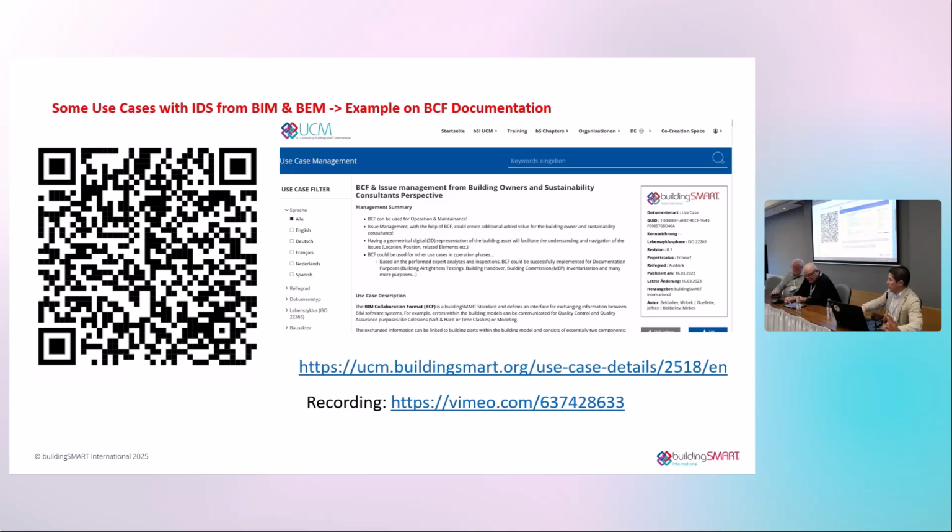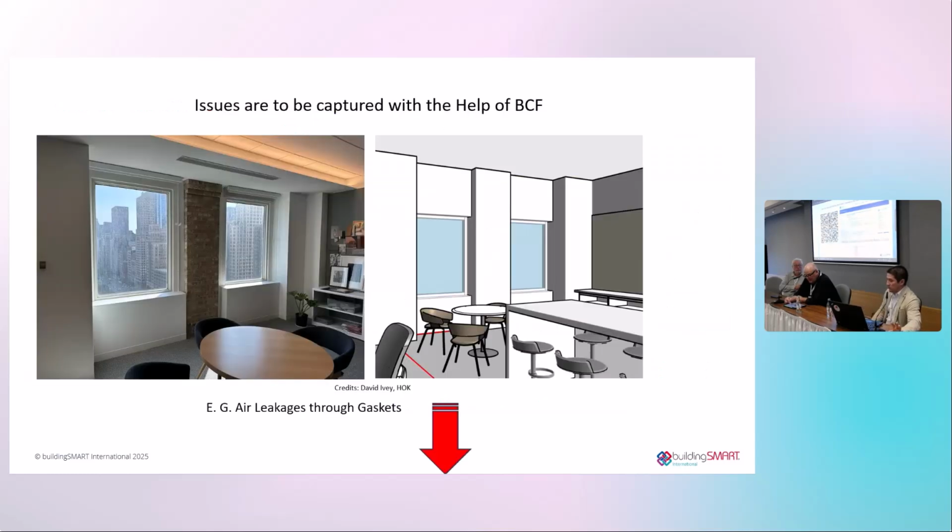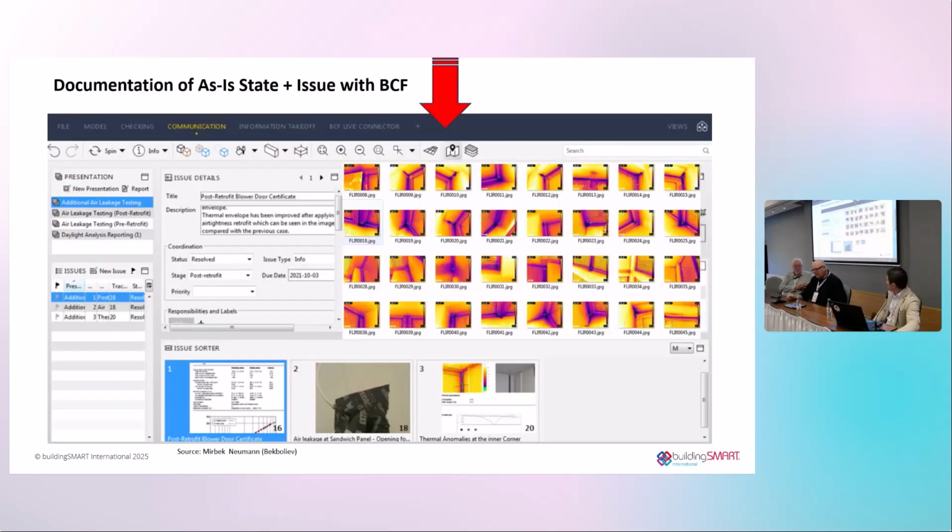You can check it later. That's what architect and client did, and it was the same case in the HOK office. So we ran a blower door test, thermal imaging, camera imaging, and as you can see, we found a lot of leakage. But there's also sort of the anecdotal increase in plug loads in the office just because people are cold or